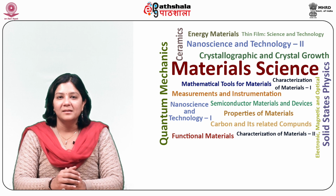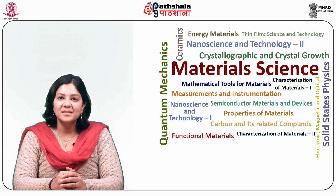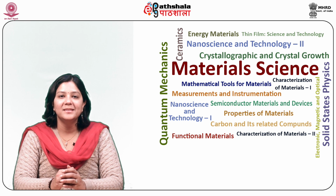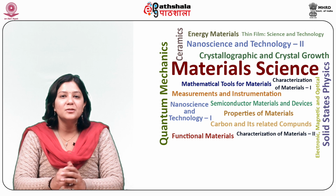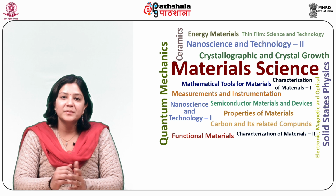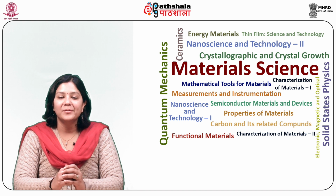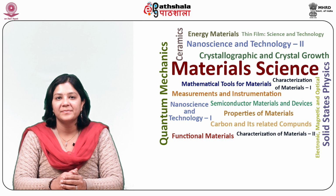Van der Pauw method. The Van der Pauw technique is employed to determine resistivity and Hall coefficient of a material. It can accurately measure the sample's property having any shape if the sample is two-dimensional, solid, without holes, and electrodes positioned on its perimeter. It uses a 4-point probe positioned around the perimeter of the sample rather than in a straight line.